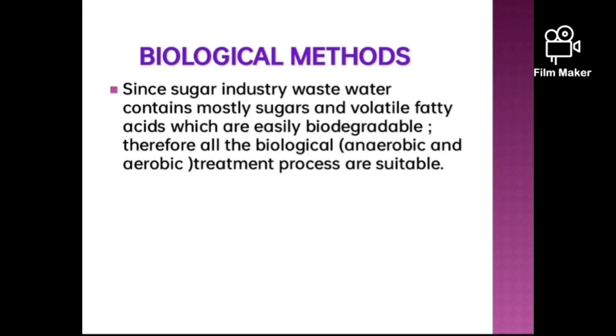Biological methods. Since sugar industry wastewater contains mostly sugars and volatile fatty acids, which are easily biodegradable, therefore, all the biological, that is anaerobic and aerobic, treatment processes are suitable.